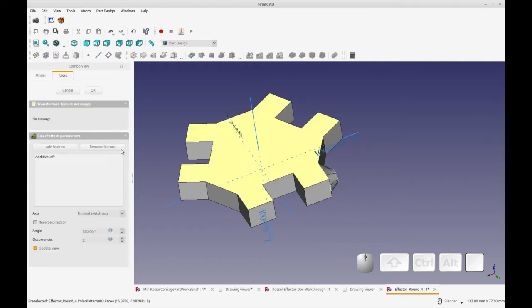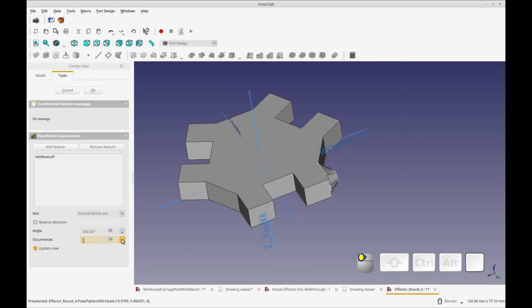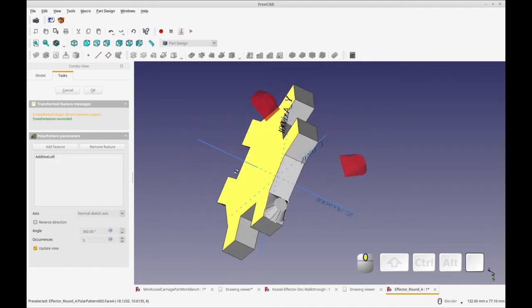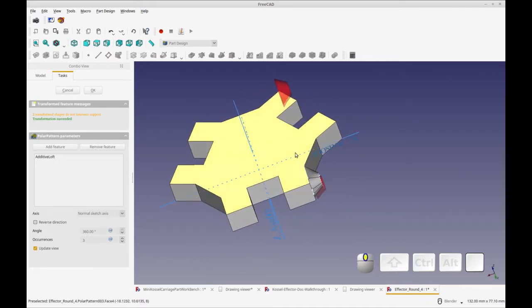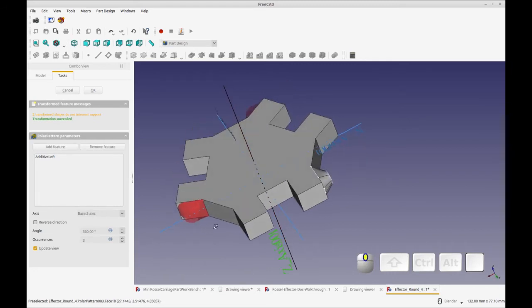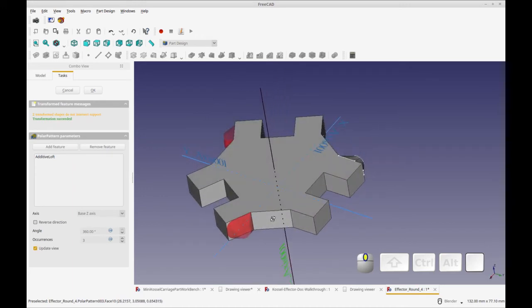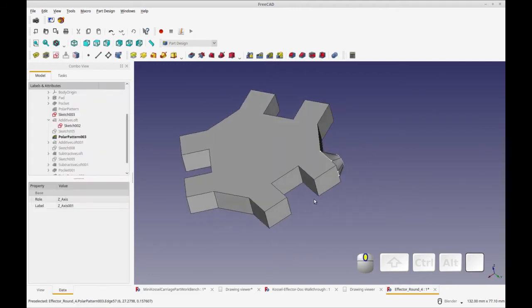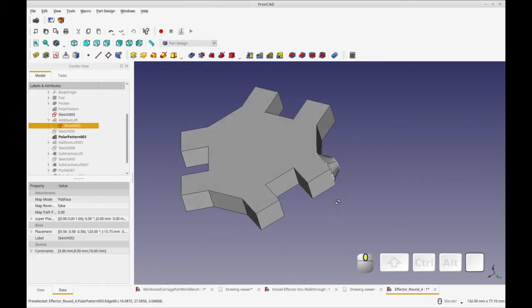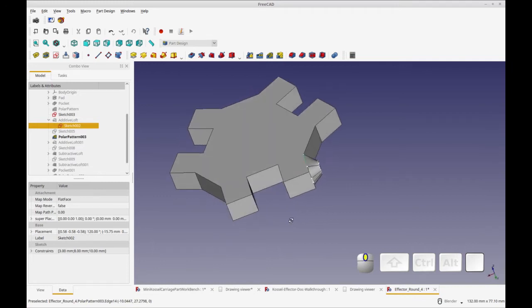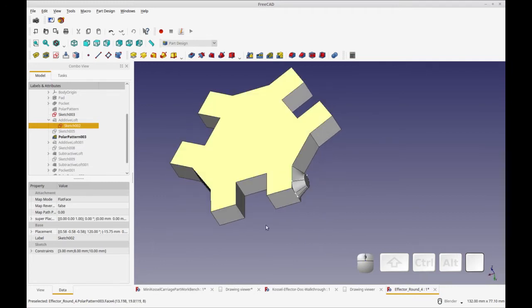So I'm going to try to do a polar array with this, with 3 occurrences. And you see when it doesn't intersect the support, it shows it as red, which I love. So I'm going to select the Z-axis so it transforms it to where I would expect it to have support, and you see it still doesn't find it. One of the things I did in the past to get the other one to work was to move the base of this sketch just a tiny bit into the object, like a tenth of a millimeter or less, and that did it, but that's not working anymore.